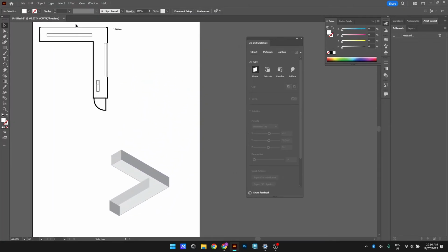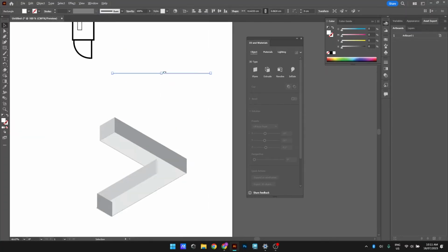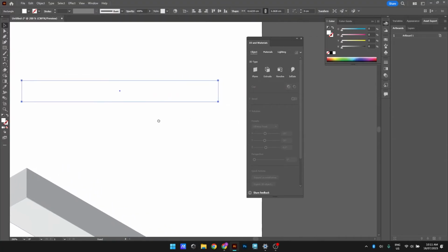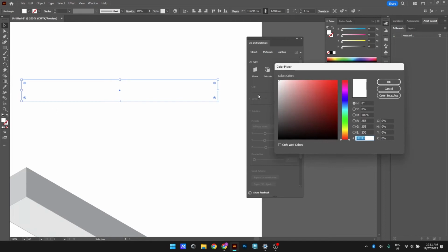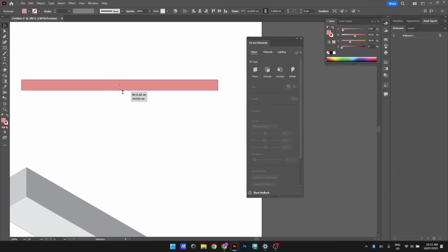I'm going to do my window to start with. So I'm actually going to click on this window, Control C, Control V. Okay, and so for this window, I'm going to zoom in, and now I'm going to stretch it down to be the height I want it to be. So I can change this color to something a bit brighter so we can see. I can make it the height I want, and at the moment you can see there it says H0.97. That's about a meter tall, which is fine.